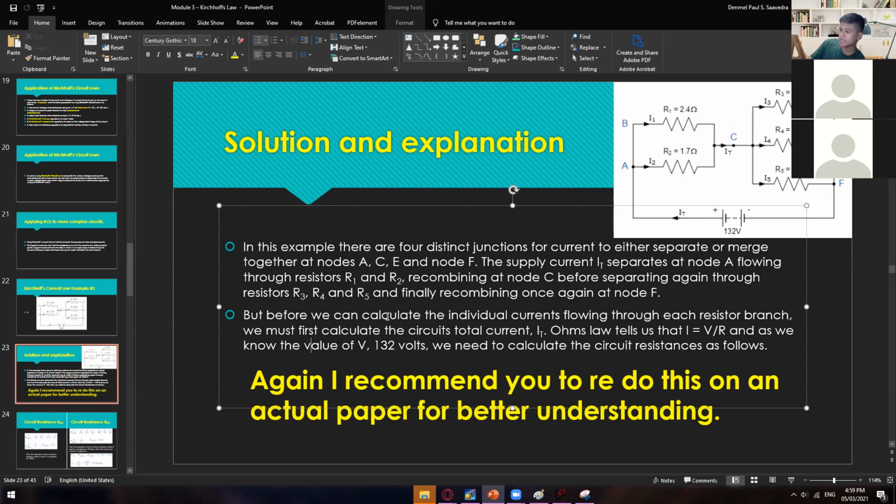But before we can calculate the individual currents flowing through each resistor branch, we must first calculate the circuit's total current, or I sub T. Ohm's law tells us that I is equal to V divided by R. And as we know, the value of V is 132 volts. So we need to calculate the circuit resistances as follows.